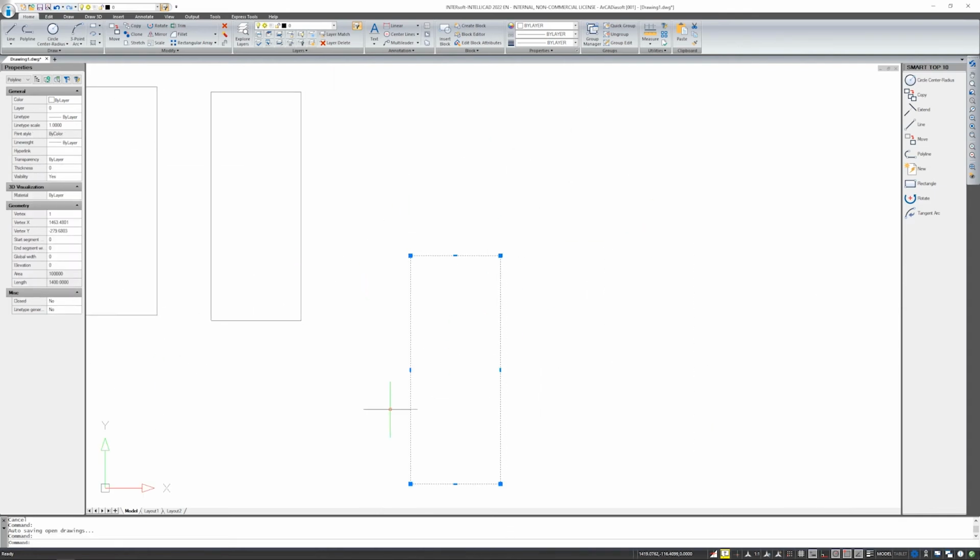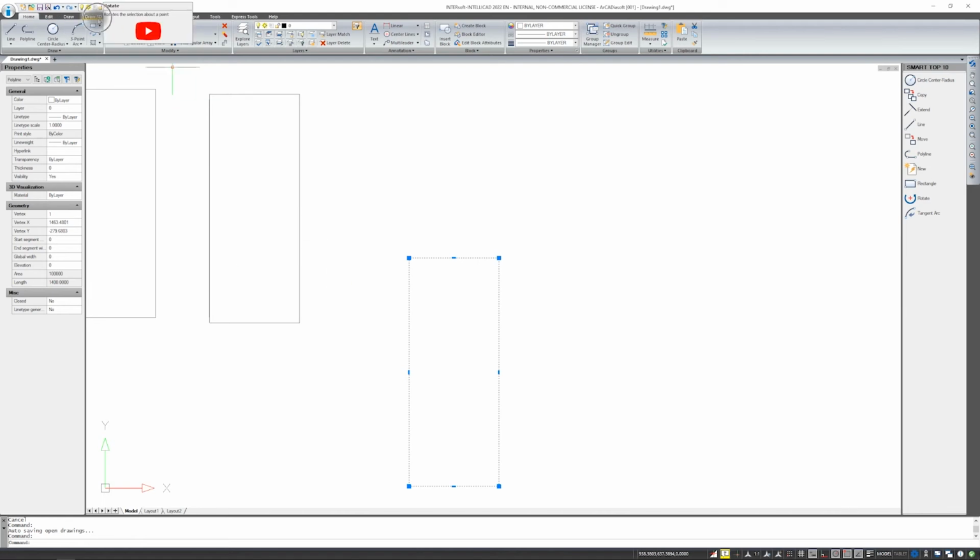A polyline on a view usually looks the same as a line, but please note how I mark it. The whole rectangle is one element, that is, it is drawn with one outline. The polyline can be closed. Then, if you would like to create a three-dimensional element from it, you can then draw it using the option on the 3D drawing ribbon.